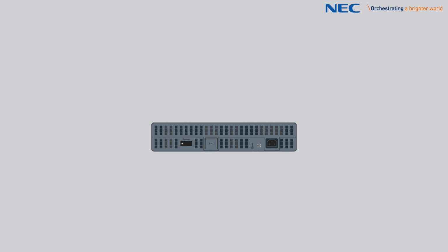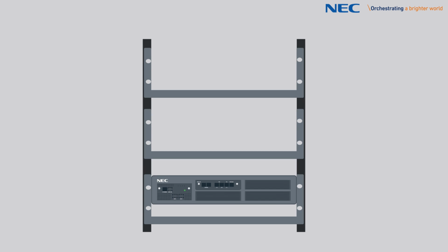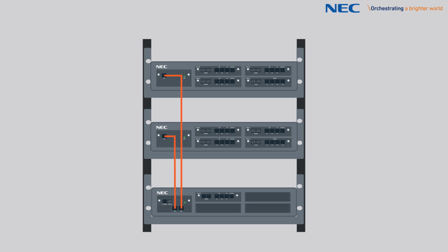Once the cabling is complete, you can power on the SL2100 system. Ensure all cards are inserted correctly before powering on the SL2100. If you have any expansion chassis installed, these should be powered on first and the main chassis last.